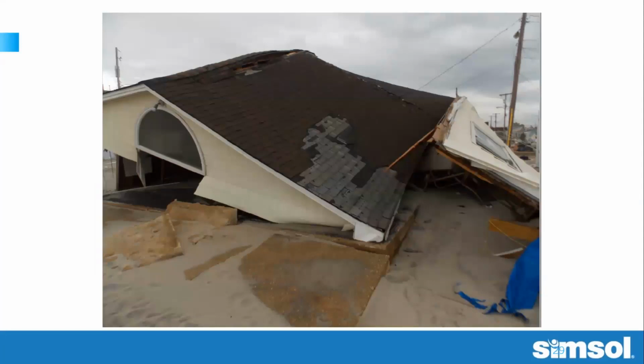Now, this one I put in just as a discussion point. You see some shingles damaged here. The building's collapsed. Notice we got two roof coverings on the building. We have the original roof covering underneath a subsequent roof covering. This particular building was damaged by flood. You notice the concrete sections of boardwalk that have pummeled the front of the building from the surge and caused the collapse of the building.